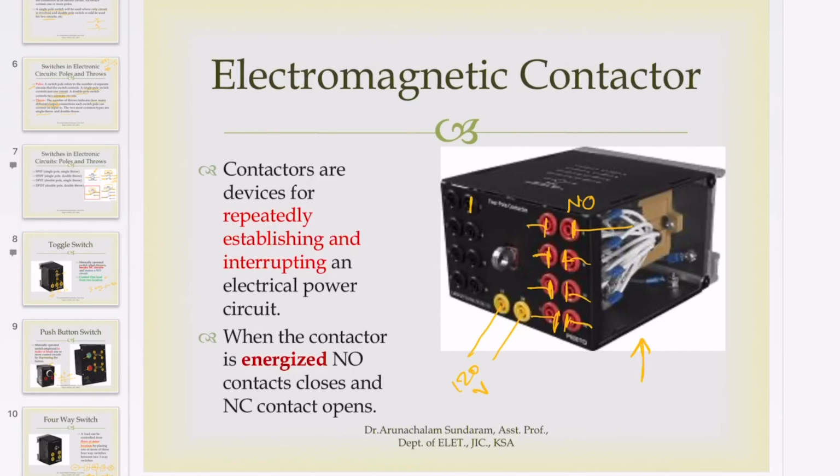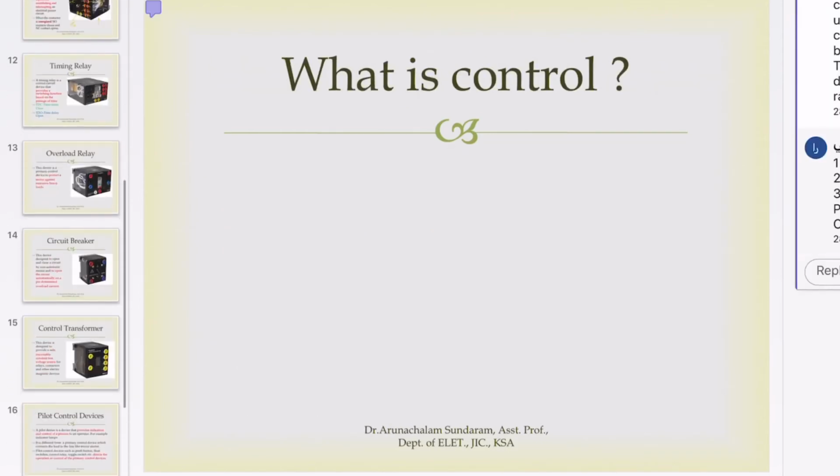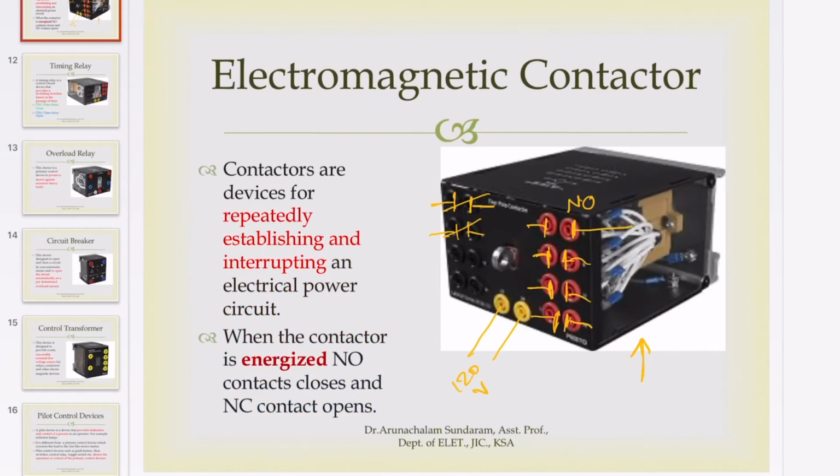Here are the normally closed contacts. So once I energize the coil here, those normally open contacts will close and those normally closed contacts will open.